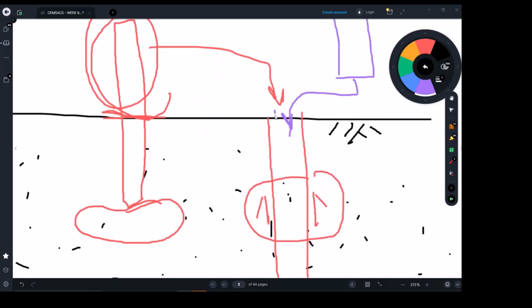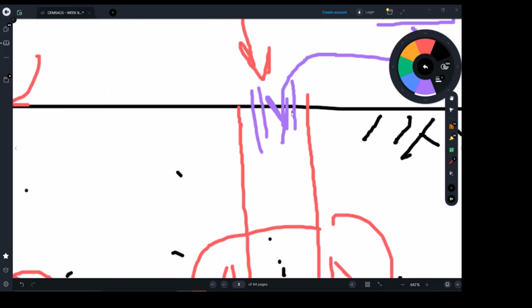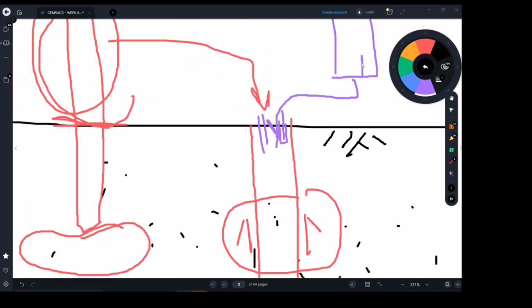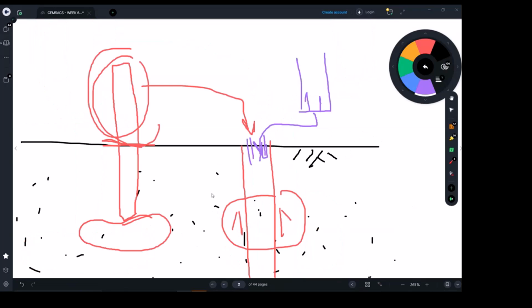Ideally, I've seen on site, when they crane these things on top, they can use some dowels to connect them together. They can just drill and put some epoxy on site, and then have another kind of drilling here too, just to have some mechanical connection between them.